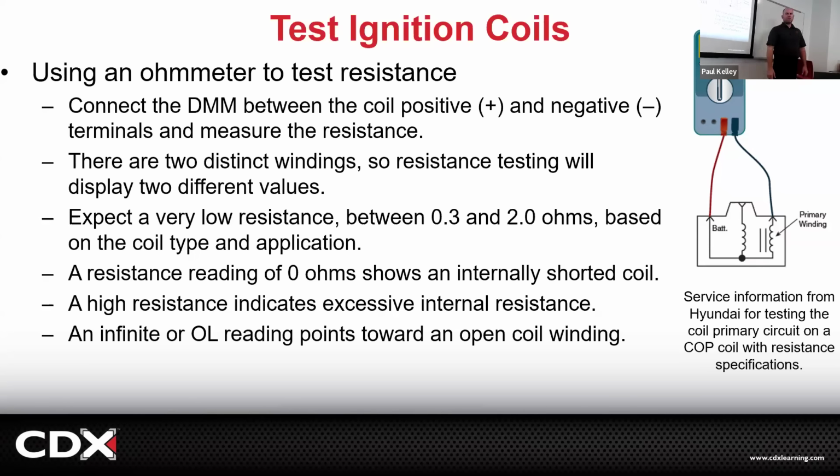That'll hold up with the manufacturer. That'll hold up with an insurance company. It's all good. That'll even hold up with somebody who brings their mechanic friend to see if your work is good. And you're like, well, what'd you do to test it? I measured the primary ignition voltage of the coil and it was OL. Okay, that's a matter of fact. So this isn't really your opinion? No, because it's a measurement and it's out of spec. Have a nice day. Okay, so pretty good.